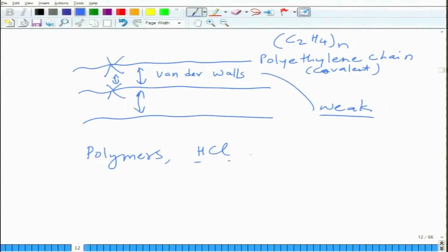things like HCl. So, many organic compounds have this kind of behavior. This could be because of a permanent dipole moment. So, materials which can have this are things like water, various polymers, PTFE, PVDF. PVDF is a material with a permanent dipole moment, still it is a polymer. So, examples are PVDF, or you can have PVC. Some of them may have a permanent moment, some of them may not, but still you will have this secondary bonding.